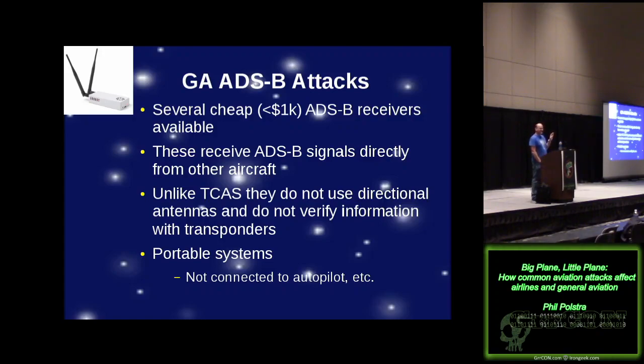What's the difference between a Stratux and a Stratus? Several hundreds of dollars. That's the difference. And Stratux sounds very Linuxy, open sourcey, cheap, right? You can buy these units, or you can build your own for less than $200. So what has it got inside? It's got a Raspberry Pi, and it's got a dual channel receiver. There are actually two channels that ADS-B is transmitted on.